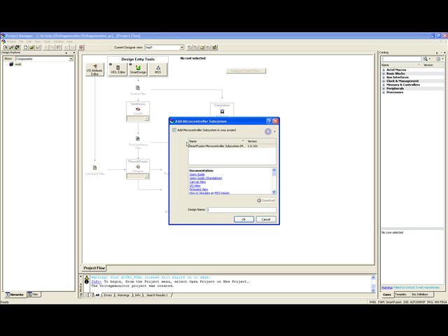Since SmartFusion has been selected as the FPGA family, the Add Microcontroller Subsystem dialog opens. The SmartFusion Microcontroller Subsystem MSS core name and version number will be showing in the window. Enter a name, such as Voltage Monitor MSS, into the Design Name window and click OK. The SmartDesign MSS configurator opens.